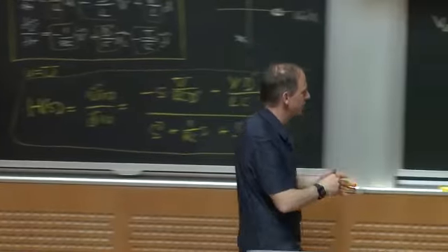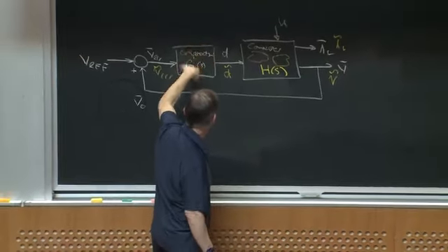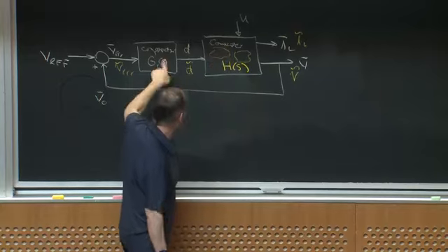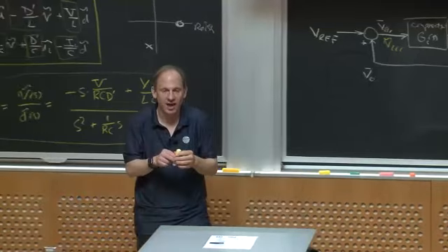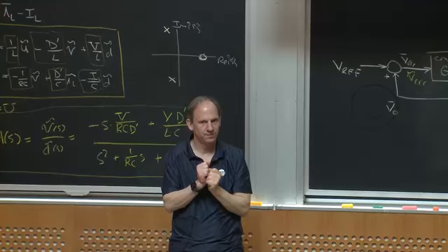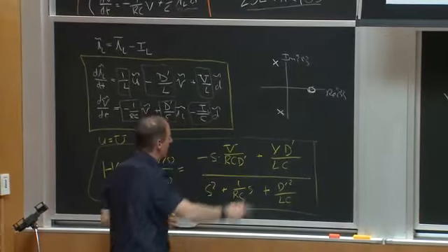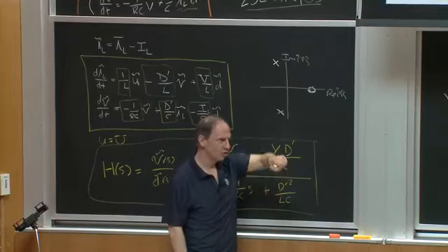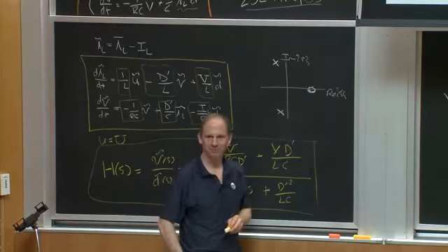Because usually if I take some system and put in some gain, forget about what this control is, say it's just a proportional gain, and I close the loop and turn up the gain, what tends to happen is the poles move, right? The idea is I had some open loop poles, and when I put a feedback loop around them, the dynamics are going to change. The closed loop poles are somewhere else, okay? But it tends to be that as I turn up the gain, the open loop poles tend to move towards the open loop 0.